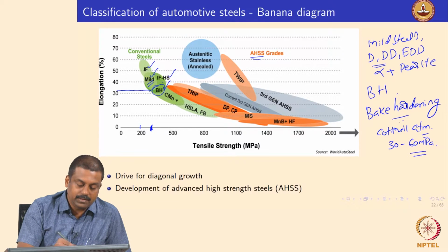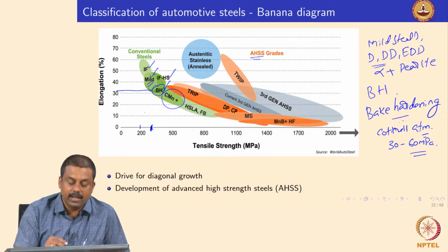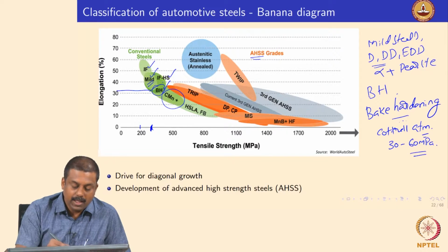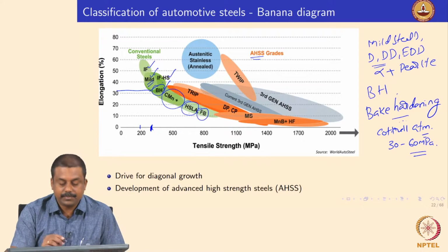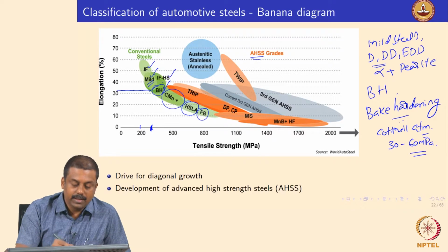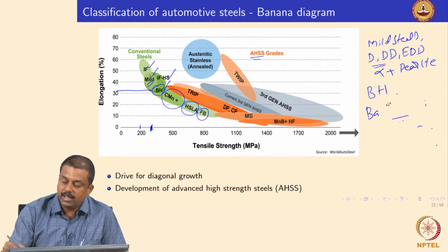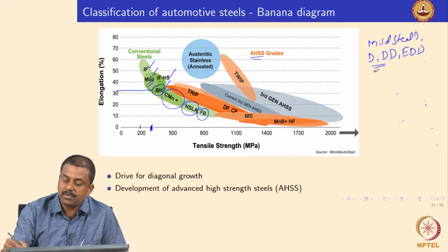were steels with an increased amount of alloying elements, for example carbon, manganese, chromium and silicon added steels, and high strength low alloyed steels, and to some extent ferritic bainitic steels. These are again simple microstructure, ferritic pearlitic containing steels with slightly higher amounts of manganese and chromium, which can provide substitutional solid solution strengthening.